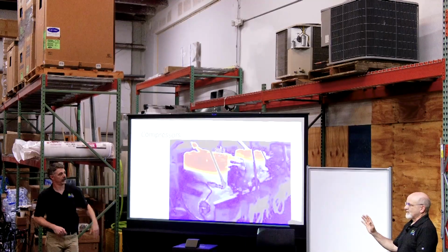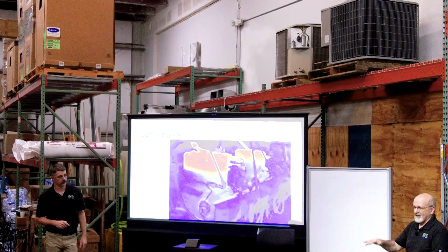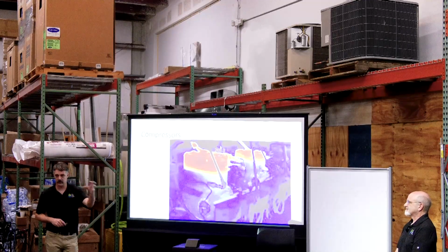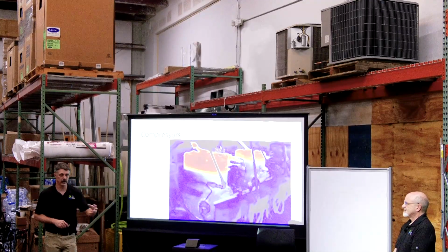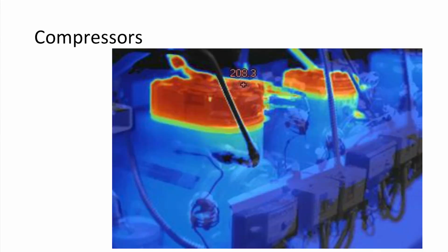I love it. Keep in mind that what you're seeing is the effect on the surface of things going on under the surface. You're watching the temperature change as the refrigerant moves through the compressor and different things open up, and unloaders turn different things on and off inside. So this is like a highlight of a compressor teardown video. If you watch one of those and know what's going on inside, it can help you interpret what's going on outside.